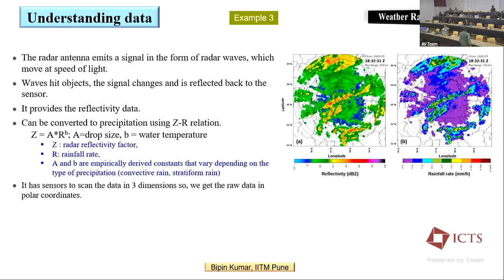What can radar do? Radar is just sending the waves and they come back as reflectivity. It can be anything. It can be a bird, an aeroplane, hail, a cloud, or a raindrop. But we are interested only in the raindrop. So the first thing is filtering. It can even be flies, these small flies. They also get reflected and we get the data. They are not droplets.